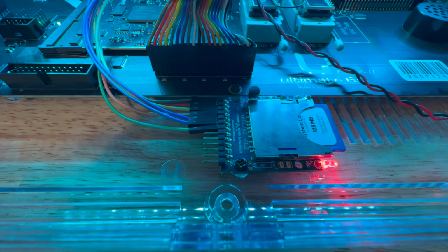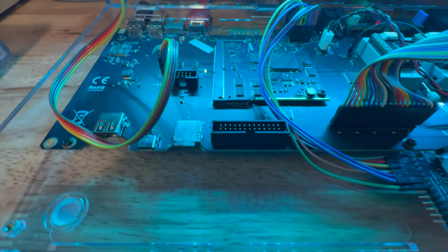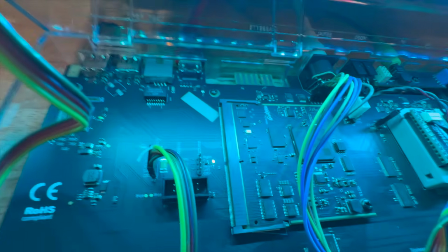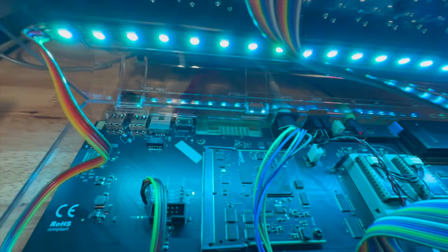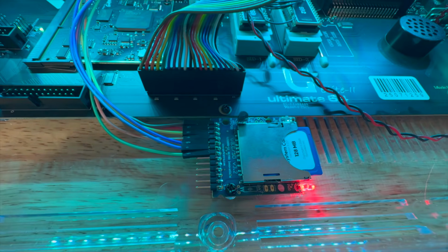Basically, I've got it here, and you'll notice that only some of the pins are used. I've got these DuPont wires running over to this header that is right behind the IEC port on the back of the device. There's a header there, and there'll be a diagram shown for you to tell what the pinout is on that header, and that header is feeding the IEC signal to this SD2IEC.